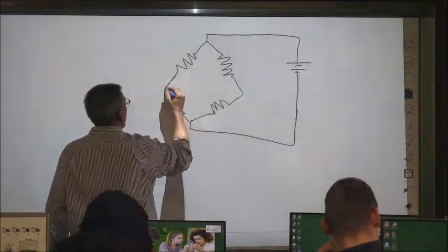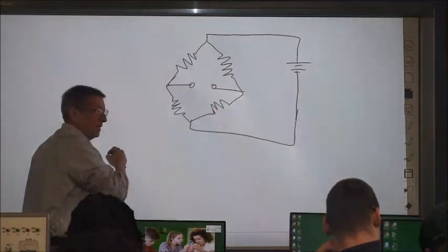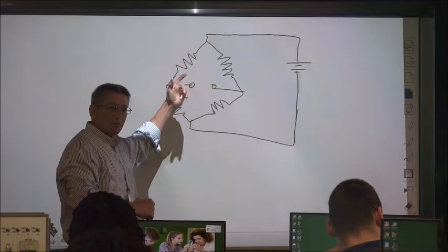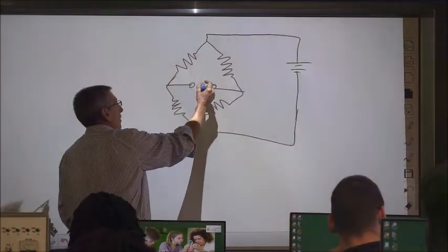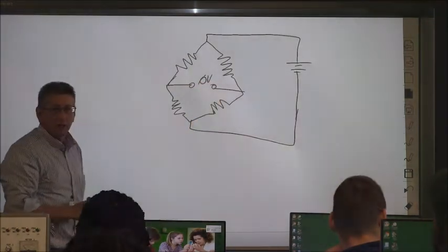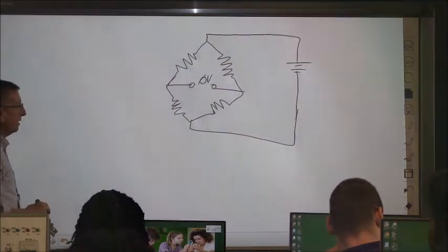If you remember the Wheatstone bridge, there's the Wheatstone bridge, and the principle behind it is all resistance values are balanced, right? So ideally, the voltage at this point is going to be 0 volts, right, in the center of that thing. That's kind of what it's based on.